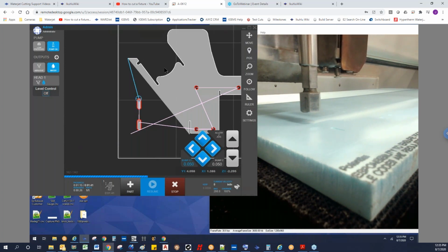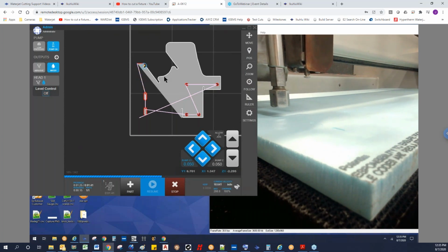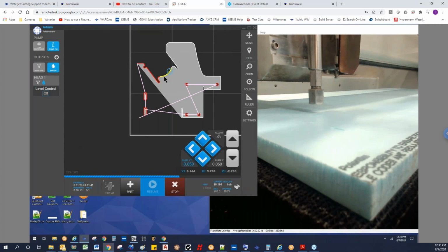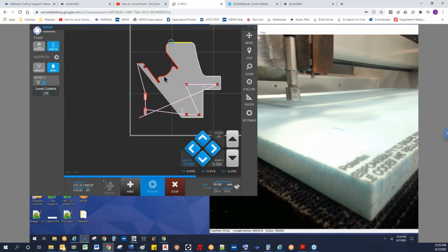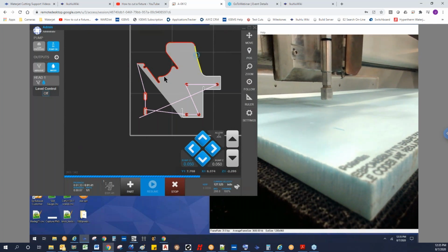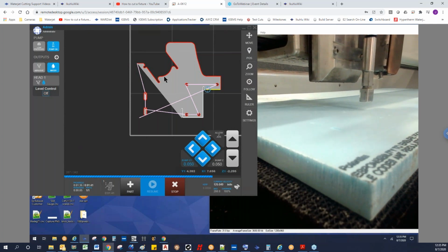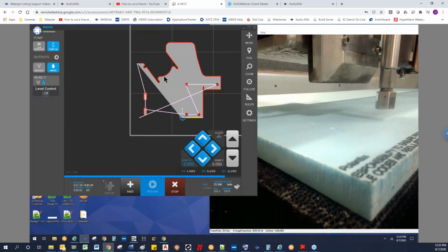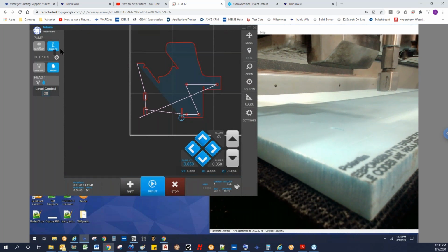So now it gets to that outside cut. And again, even though it's got the C's in there for rotation, if it were a 5-axis machine, since it's 2D, it's just going to ignore those and cut it as a 2D cut. So that's a little bit of an easier way to program a part where you've got open contour cuts. Just tell the machine that it's a 5-axis machine, and then set that angle for the cut to 0, and then makes it quite a bit easier. So we'll go ahead and turn that off.